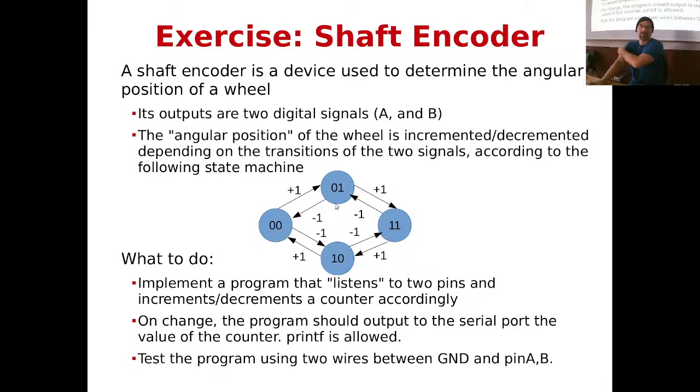Some of you might have asked, what is the state machine? The state machine is the state machine to decode the encoders. When you have a 2-phase encoder attached on a robot, basically you have 2 light emitters and then 2 light receivers. And then when the shaft of the encoder goes from the left to the right, let's say one ray and the other ray, right? Now, if something goes in between this ray, then you register a 0.